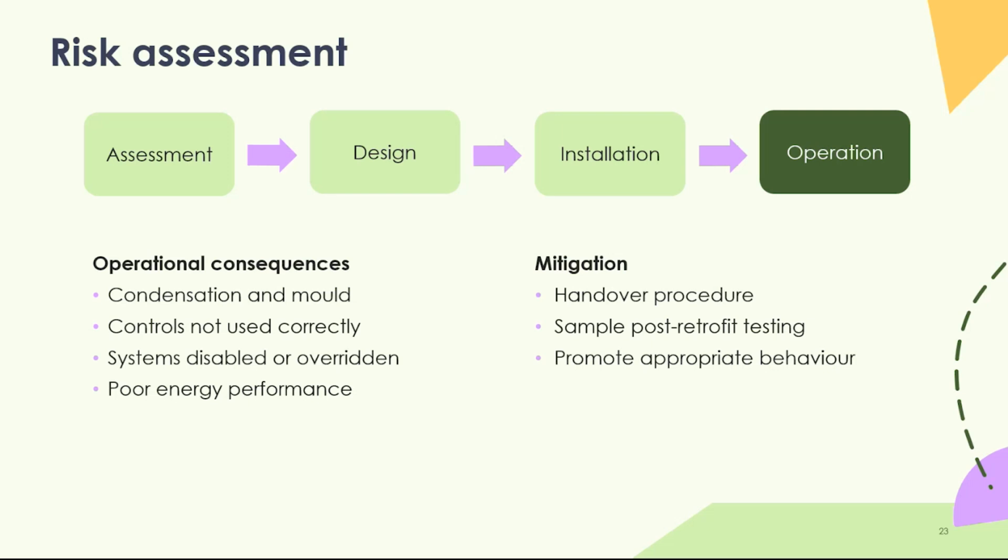And sampling your post-retrofit testing. So have a sample, do some airtightness tests, maybe some thermography, to just get the thermal camera out, try and spot any cold spots, those sorts of things. Some way to understand that, okay, this is performing properly or this isn't.